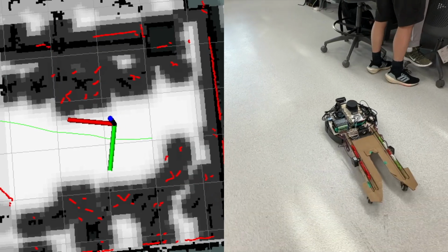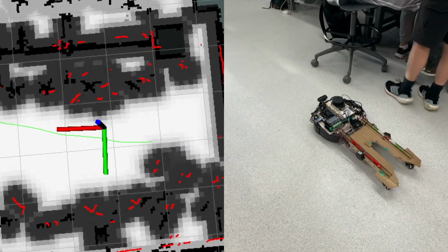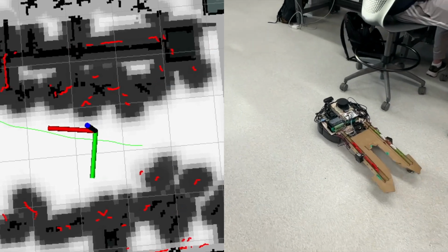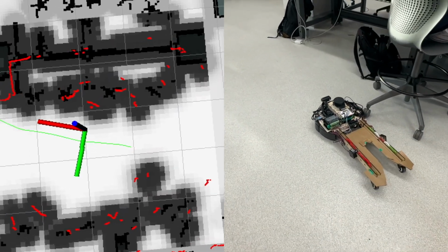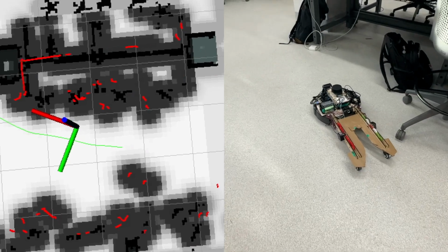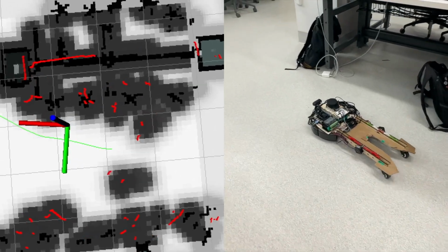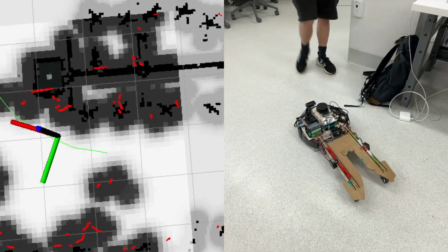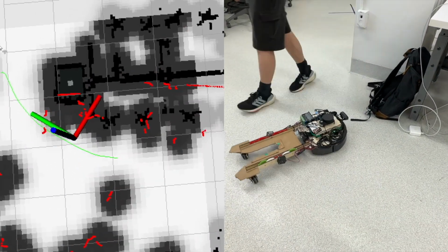Localization is the process of identifying the robot's location, which uses the pre-made map, LiDAR, and odometry data. This is combined in a ROS package called AMCL that determines our location and orientation when moving around an office. Another package called Global Planner creates a path from the current location of the robot to a goal destination using Dijkstra's, a shortest path algorithm. The NavStack also includes a local path planner, which detects and navigates around new obstacles that were not on the pre-made map.